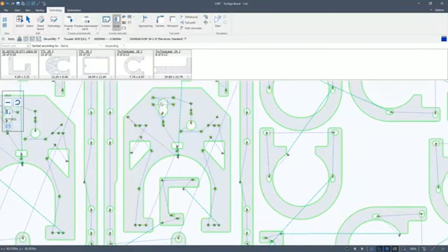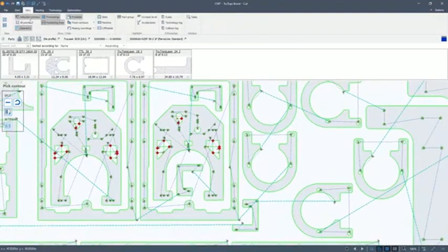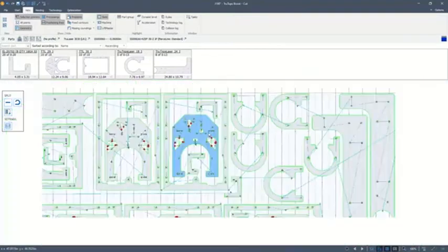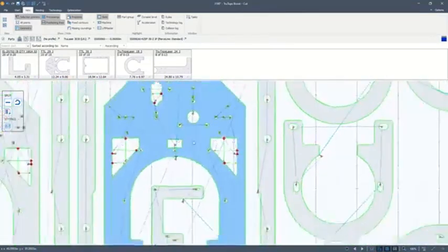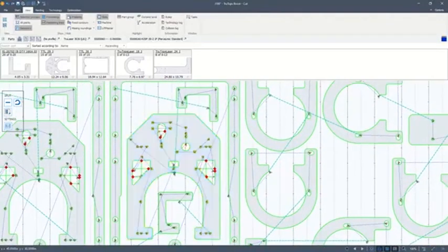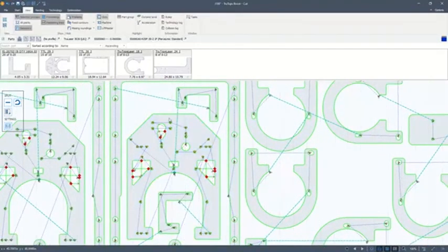And let's just say we're a little concerned with these arbitrary contours, maybe getting hung up in the slats or getting stuck because of their shape. So let's go ahead and, rather than tab them, we'll cut them up into smaller pieces so they fall through the slats easier. And you can see here, I'm also viewing my slats as well. So my slat layout or my table is here. So the software can use that to determine if anything is a tilting hazard and react to it accordingly.